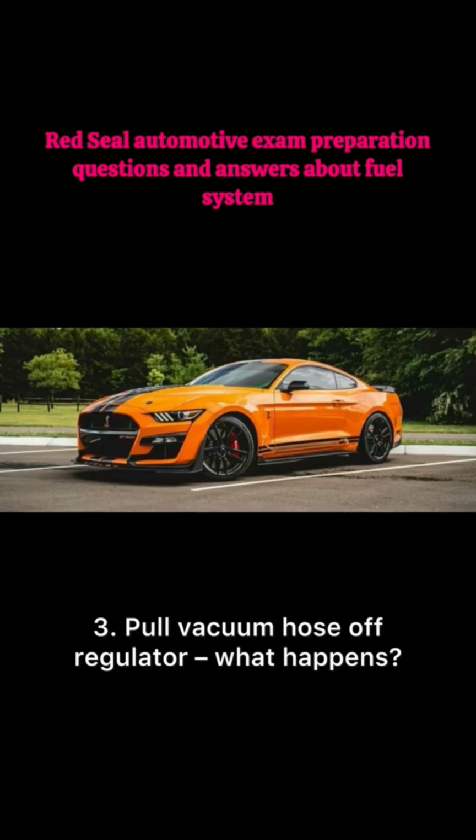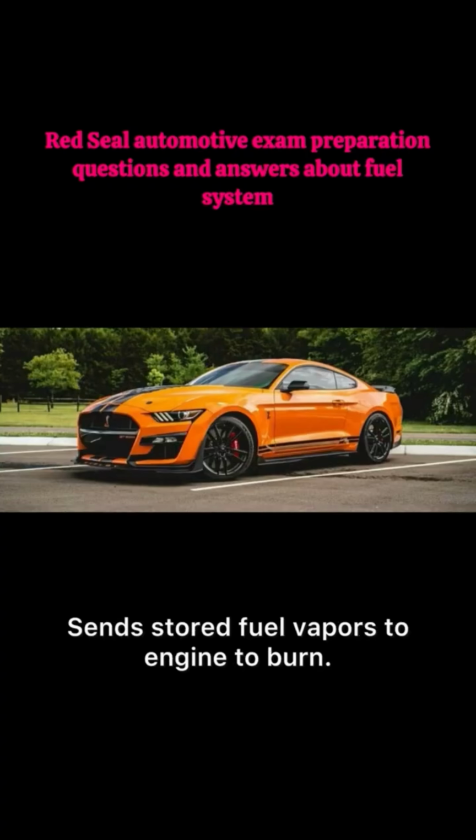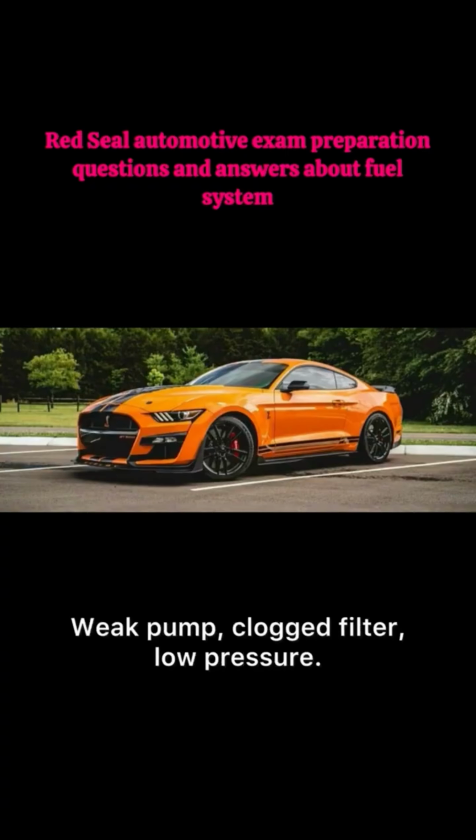3. Pull vacuum hose off regulator. What happens? Pressure goes up 5-10 psi. 4. EVAP purge valve job. Sends stored fuel vapors to engine to burn. 5. P0171 lean. Fuel system cause. Weak pump, clogged filter, low pressure.